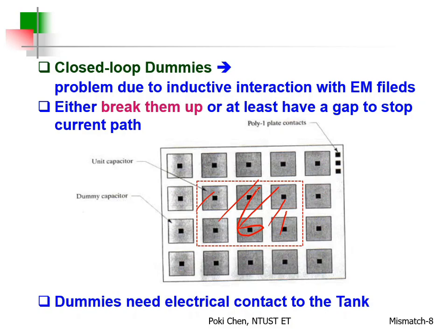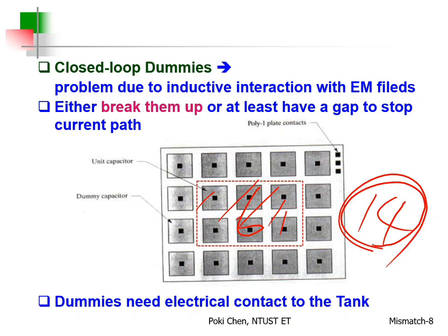To protect 6, totally, you have 14. To protect 6, you make 14 for protection. Oh, that is too much. Okay? So, lesson 2. You don't need to use the same size for dummies. No. The golden rule is the spacing needs to be the same. Okay? But I don't tell you need to use the same size for dummies. No.